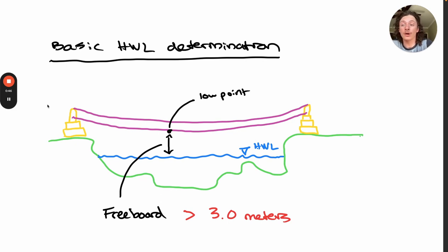A lot more information and specific processes go into actually determining this high water line: who we chat with at the community, when and how we chat with them, and how we verify this by being on site and checking for signs of erosion and signs of storms. But all this information and the process we go through is tabulated or discussed in the Site Feasibility and Surveying